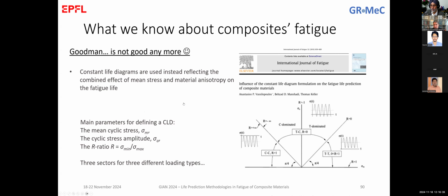We will discuss again in detail about these constant life diagrams, but what we should keep here is that the Goodman diagram is not anymore valid for composites.